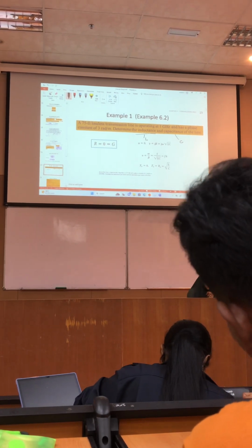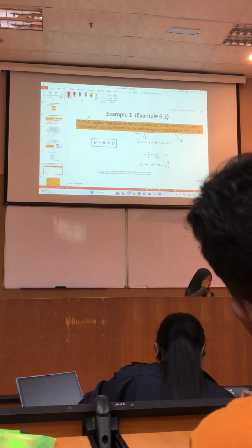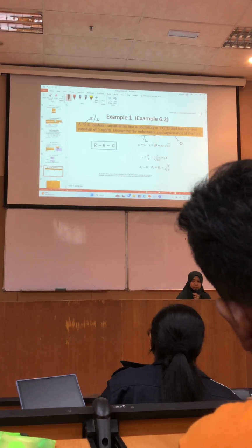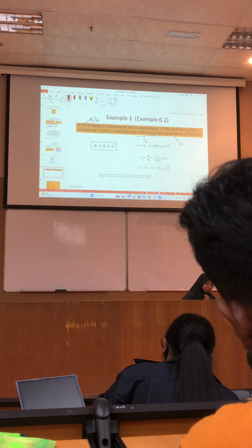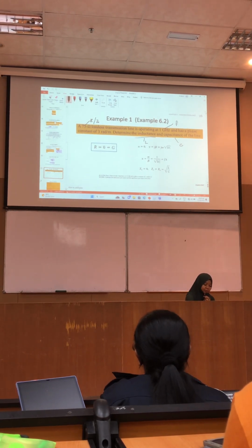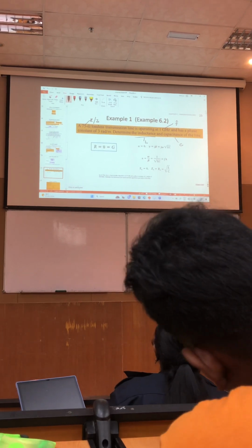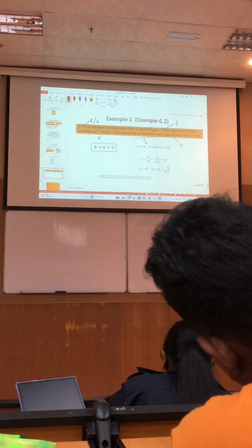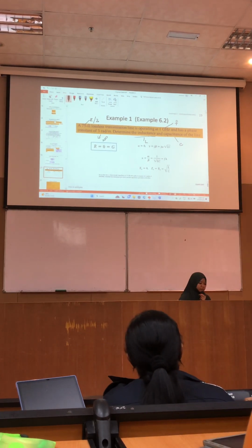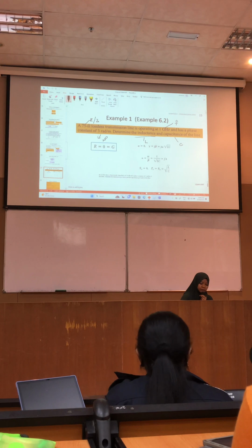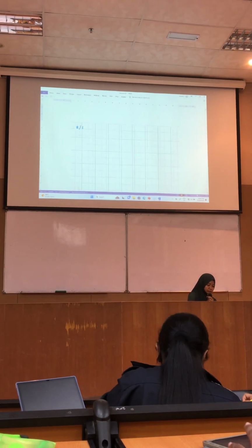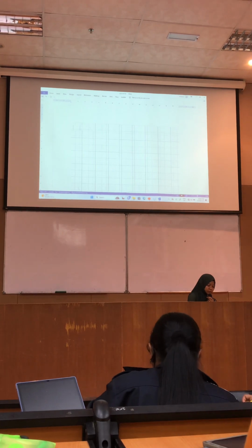Given 70 ohm, which is basically R or Z naught. 1 gigahertz is the frequency. 3 radians per meter is the phase constant. Alpha or beta? Beta, good. So pull out the parameters first. R or Z, since R equals 0.